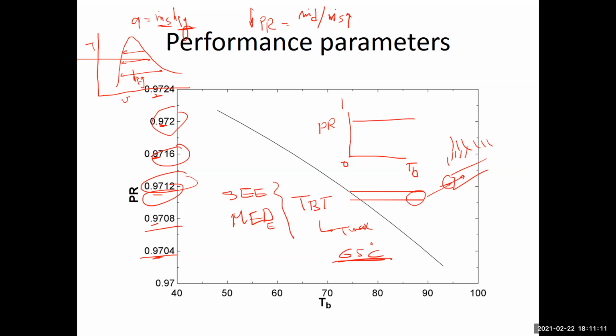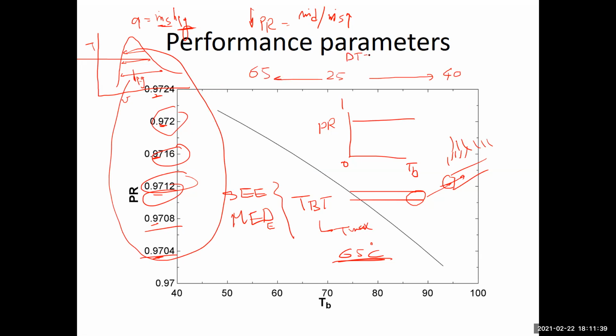If you purify your water from these components, you can increase the temperature to 85 or maybe a little bit more. When you increase it to 85, it's not because of that, but because we know that if the maximum limit is 65 and the lower limit is 40, then the temperature difference across the whole desalination system is 25. If you have a delta T per stage equal to 3, then you can have 8 effects only. But if this one is going to be 85, then you can have much more than that. You can have 13 effects, 14 effects. So you can produce more and more water for the same input quantity of steam at the first effect. We'll talk about this in detail when we get to the MED system, but I was reminded of it when talking about the changes in the PR here.